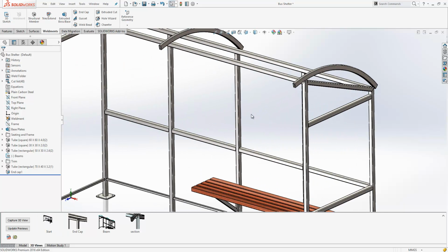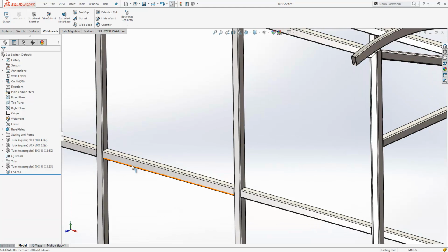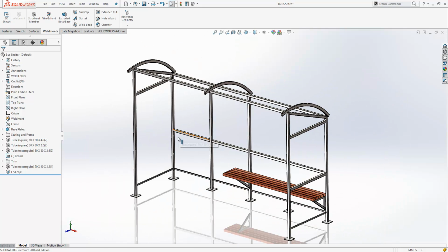At assembly level we've had the ability to use the tab key to hide components since around 2012 from memory. That functionality never existed in the multi-body modelling environment, whereas now you'll see if I hit the tab key on one of these components that it hides it away. And if we use Shift Tab, it brings the component back. So it's just a really nice way for us to navigate around our model and brings it more in line with the behaviour that we have at assembly level. This will also work with surface bodies as well as solids.